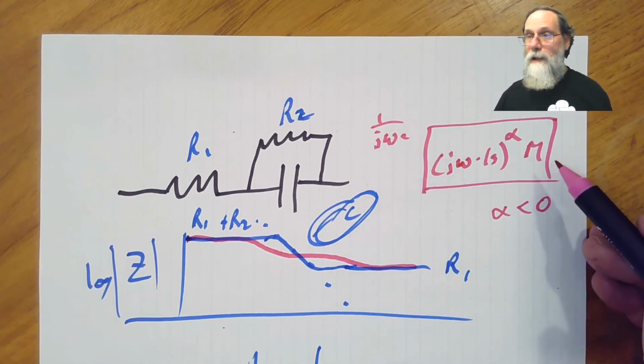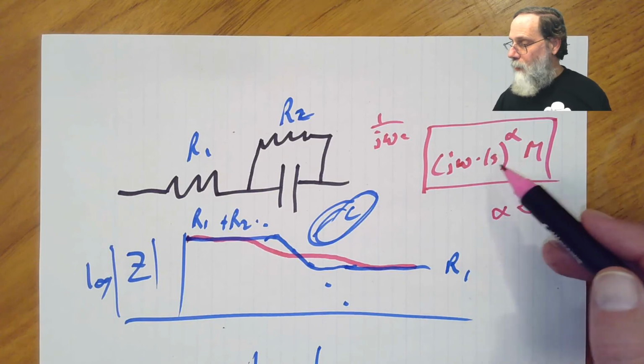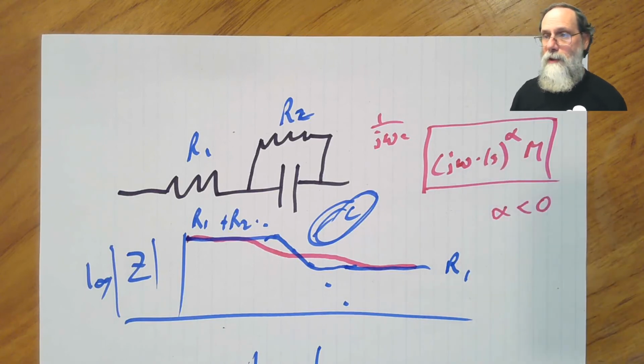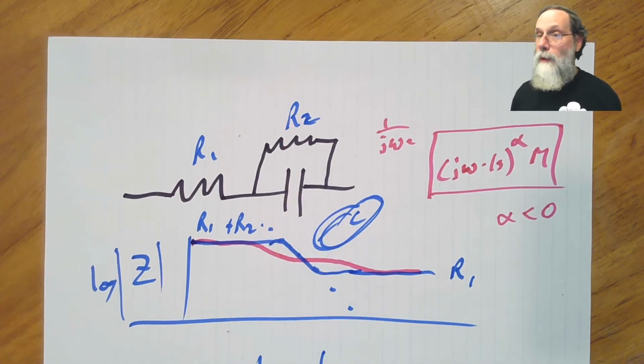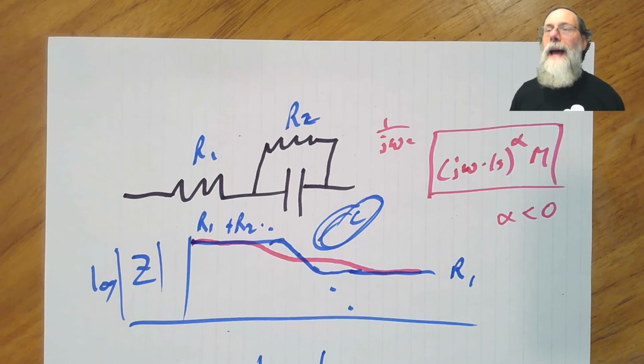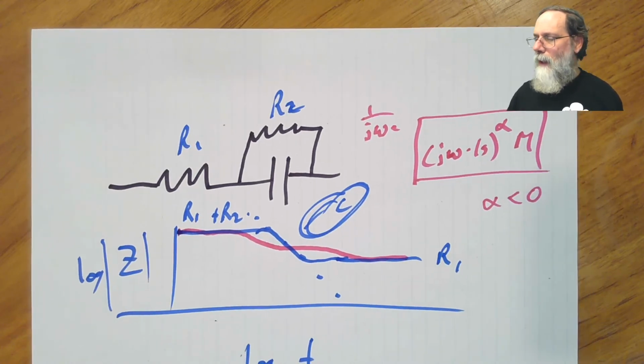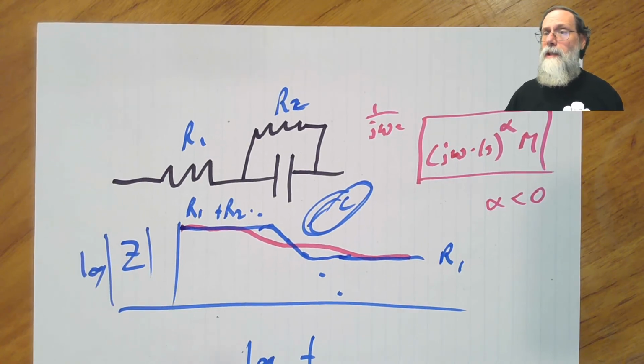And m here is again going to be in ohms because, by putting the 1 second times omega here, we've made that unitless. So we can model things that look like electrodes pretty reasonably with 3 components, one of which is the 2-parameter capacitor-like nonlinear impedance.